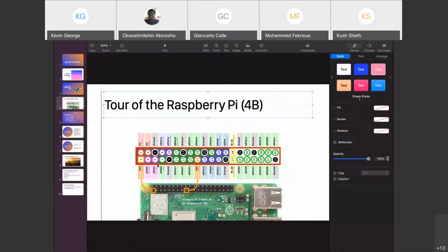Our pin 1 is going to go to a resistor to one end of the push button. And then another end is going to go into, let's use pin 11 again. So let me see if I can wire that up and show you guys how that's going to look.